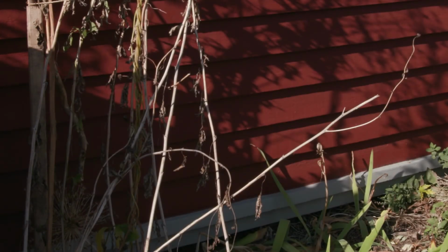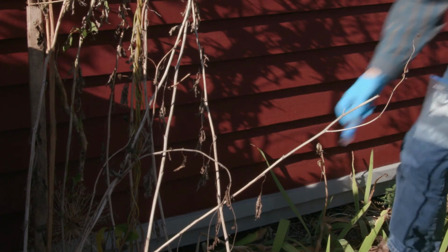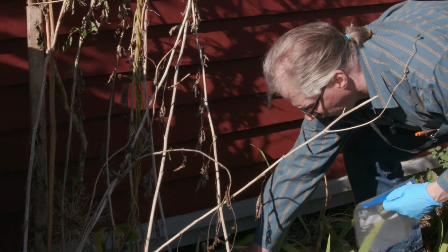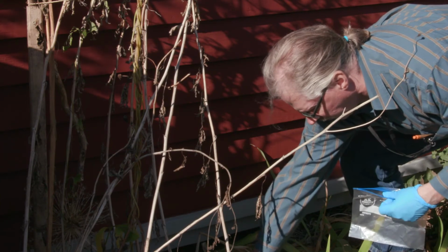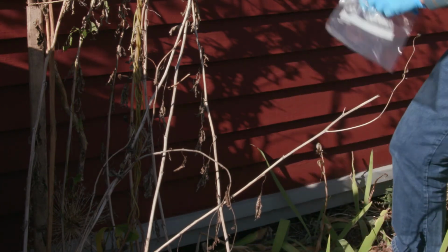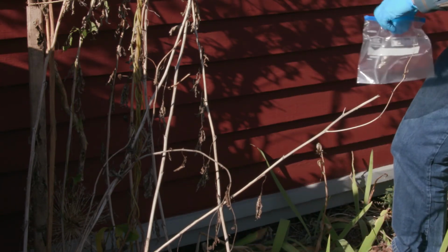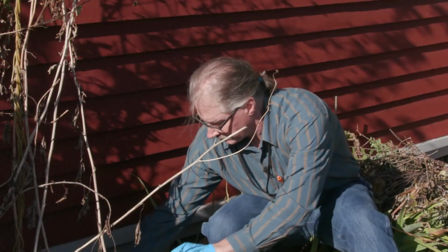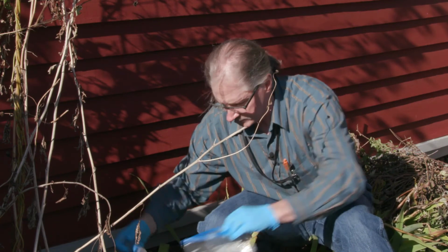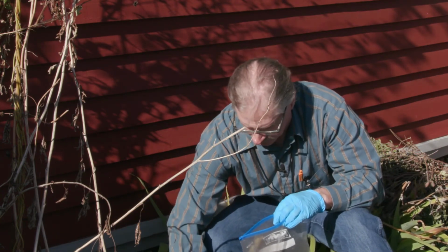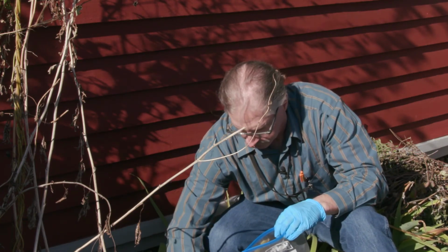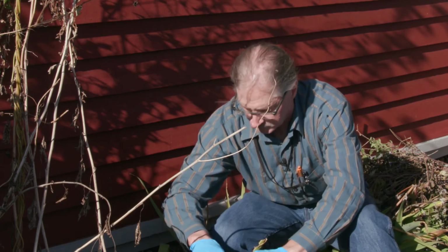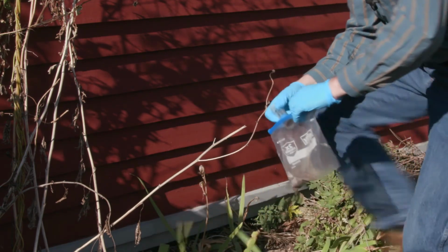If areas of bare soil were identified during your visual assessment, collect 1 composite soil sample from each play area you identified and 1 composite sample from other areas of bare soil you found. Composite soil samples are made up of 3 to 10 small subsamples of the top 5/8 inch of soil. These subsamples should be from randomly selected locations within the area of bare soil.